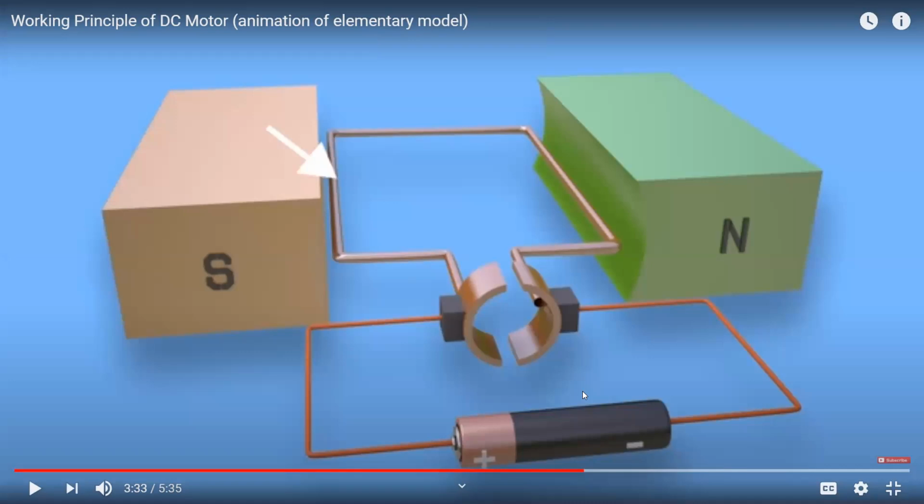Okay. So the DC motor principle is, in one line you can state that whenever a current carrying conductor is placed in a magnetic field, it experiences a force. And the direction of force is given by Fleming's left hand rule. Then you can see in this picture, 2 magnets are there, permanent magnets, south pole and the north pole. These 2 magnets are shown, and there is one armature conductor. So this is an armature which is placed between these 2 magnets, north and south pole, and that square armature is connected to a DC battery through this commutator and brush arrangement.